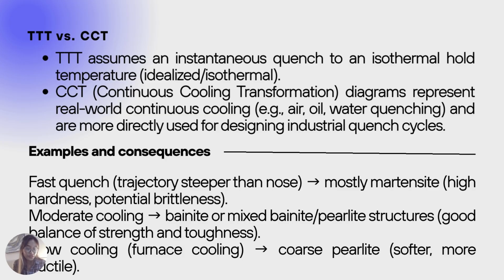So, what's the difference between a TTT diagram versus a CCT, continuous cooling transformation diagram? In short, the TTT diagram is theoretical and helps explain transformation behavior. CCT diagrams are practical. They guide real-world heat treatment processes by showing how cooling rate affects the microstructure and properties.